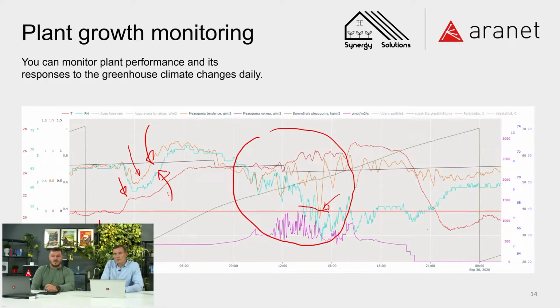Then, when I told you about using the hour meter for the lights, this is where we use it. We measure PAR inside of the greenhouse, and at the same time we are also calculating the artificial light by switching on and off, and here you see steps, and there we know when we switched each of the strings off. In this particular project we have a LED top light divided in two parts, 50-50: top light LED and interlight. And the second switch step is LED interlight.